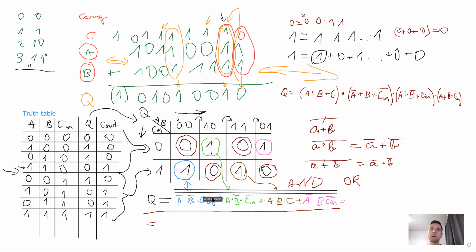If we have a logic equation, and we invert it once and then we invert it once more, nothing changes because we changed and then we changed back. What we can do is we break the bottom line over each of these plus signs. So we have these terms. I will write brackets here. Because multiplication is done first, they are not mandatory, but I optionally choose to write them in this way.